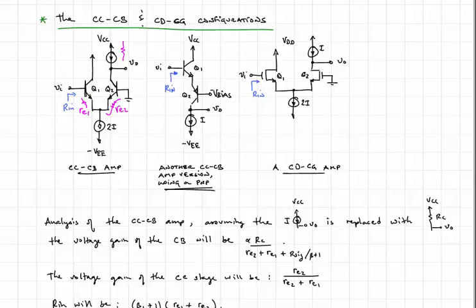Now we got away from that a bit when we put in a decoupling cap. We were able to bias the gate or the base up with some pull-up resistors or resistor dividers, and then put a coupling cap so that VI could be zero reference, and didn't have to have an offset. But here this is DC coupled, and VI is at a nominal quiescent voltage of 0 volts. So that is another characteristic of this amplifier.